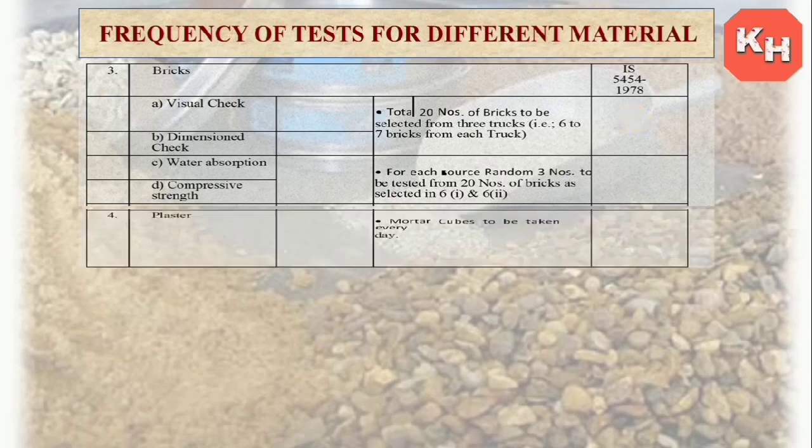Plaster. For plaster, we have to check mortar cubes to be taken every day. Whatever daily plastering work we do, for that daily work we have to take mortar cubes.